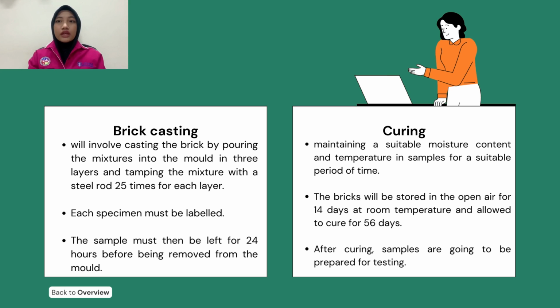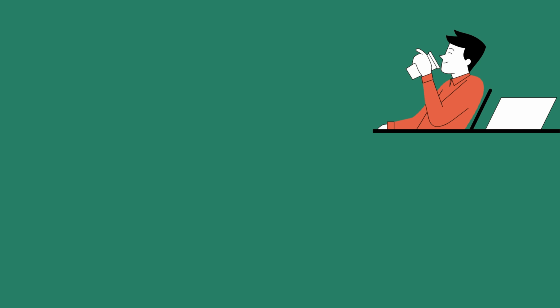For the curing, we maintain a suitable moisture content and temperature in the samples for a suitable period of time. The bricks will be stored in the open air for 14 days at room temperature and allowed to cure for 56 days. After curing, samples are going to be prepared for the next testing.